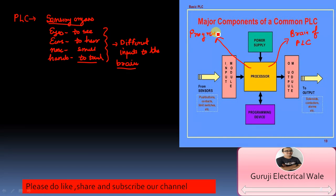The brain of the PLC is the processor where you have the program. Depending upon the conditions that you have created in the program, your processor runs that program and gives you the desired outputs, which are given to the output module. To this output module, n number of actuators are connected: contactors, relays, solenoids. So you can say that the processor is acting as a link between the input module and the output module.